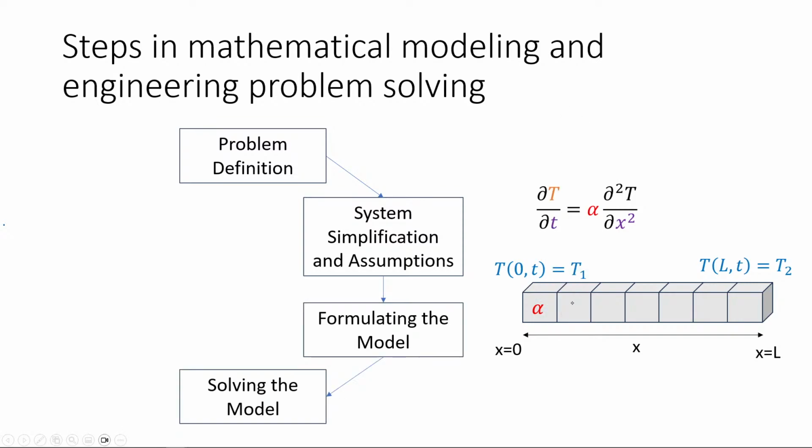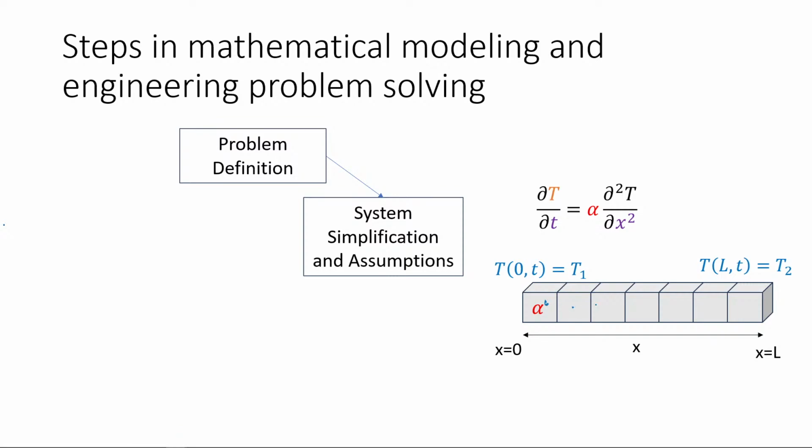one simplifying assumption, for example, I could neglect here loss to the surrounding, if that is defining a geothermal system, for example. I could, for example, assume constant thermal properties if that is a valid assumption. So thermal conductivity, specific heat capacity, the density of the rod, I can just assume that this is constant. So if that is constant, then I can bring this guy out. So this guy is not changing with x anymore.